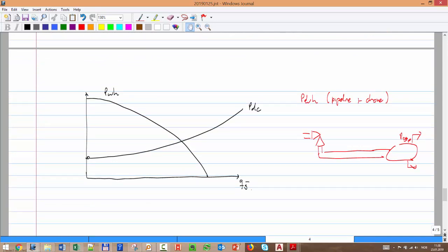What should happen if I have a choke now, okay? If I have no flow, doesn't matter. The pressure here should be equal to separator pressure. Now, if I increase the flow and I have a choke which is, let's say, 50% closed, I have the original pressure drop, right? Let's say now I'm producing this rate. I have the original pressure drop, which came from here to here, plus an additional pressure drop due to the choke. Therefore, the curve will be shifted up like that.